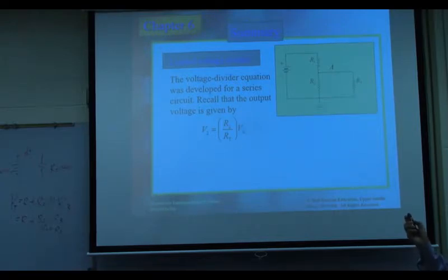But that works. This one is 3.7, and this one is something you choose, and this one is something you design, then you make this one equal 2.5. So that is how you design this voltage divider. But as I said, this is not a good way because that will waste a lot of energy. We have much smarter ways to get fractions of voltage. That will be in higher level classes, not here. But anyway, once we get this voltage divider, we need to connect it to a load. This load has a resistance. So that is called a loaded voltage divider.